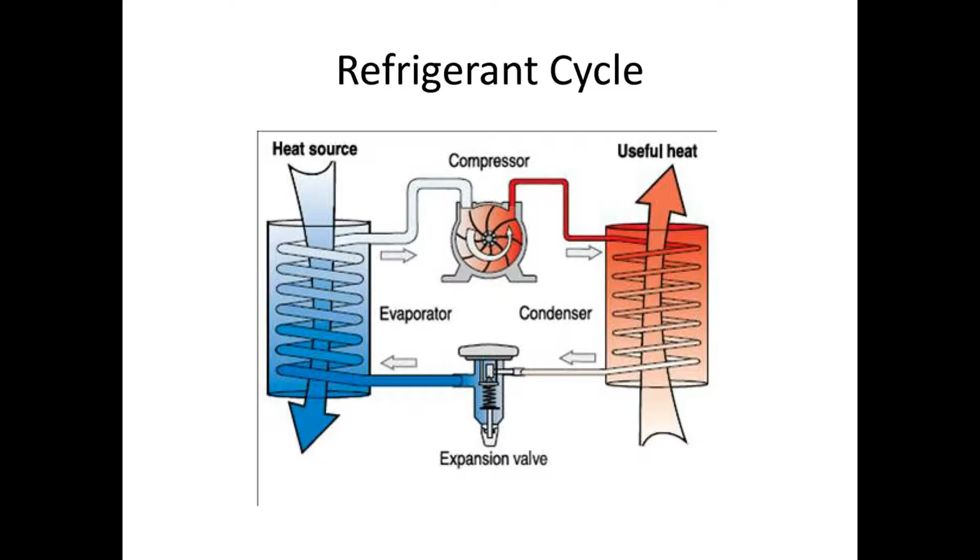through a coil. And so then it sends that refrigerant gas to the air handler. And at the air handler, it goes through what's called an expansion valve. Well, see, this gas has had a lot of heat removed out of it. And when it goes through the expansion valve, it basically releases the pressure inside the cooling coil in the air handler. And when it does this, it makes a phase change and it gets very cold.